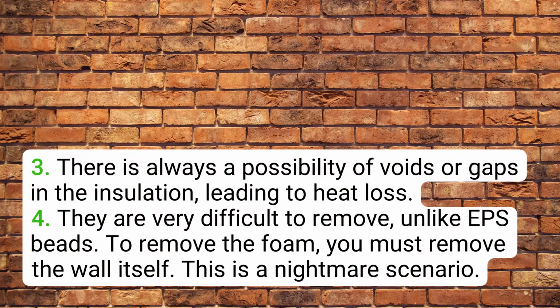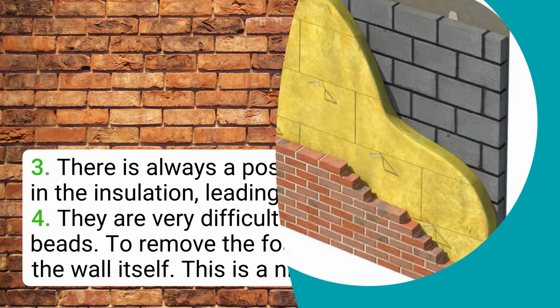3. There is always a possibility of voids or gaps in the insulation, leading to heat loss. 4. It is very difficult to remove, unlike EPS beads. To remove the foam, you must remove the wall itself. This is a nightmare scenario.